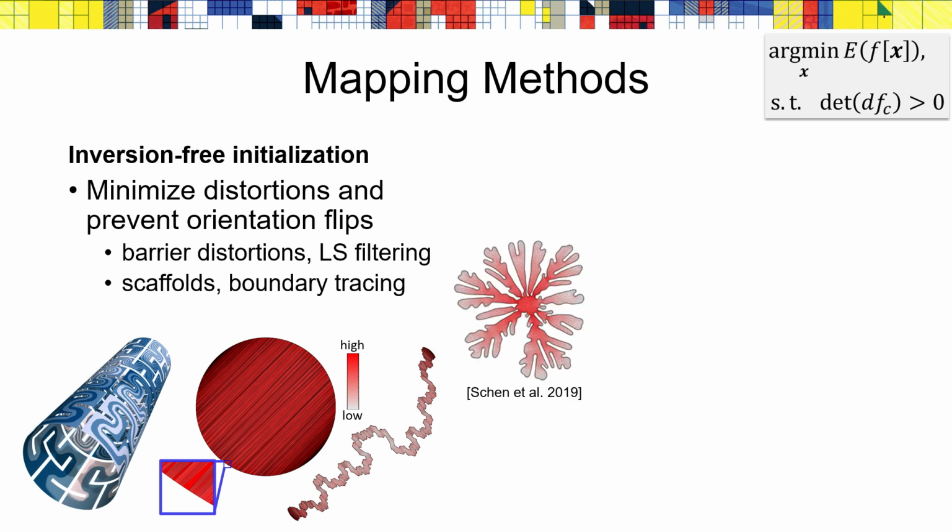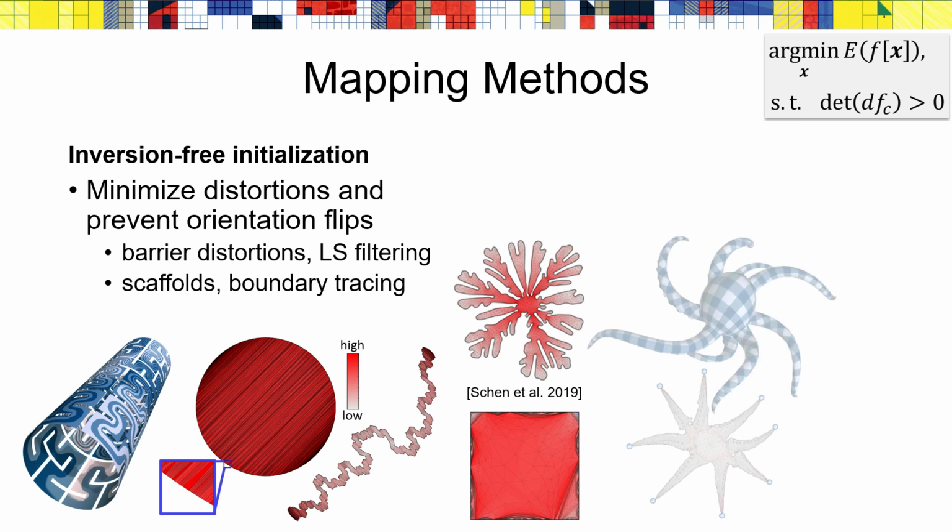Despite having theoretical guarantees, in practice Tutte embedding has certain implementation-related limitations. With floating point arithmetic and on challenging meshes, it can fail to produce inversion-free maps even if the target domain is convex. Another common case in which it's not easy to compute an inversion-free initialization is constrained parameterization with anchor points fixed in the plane by given hard positional constraints.